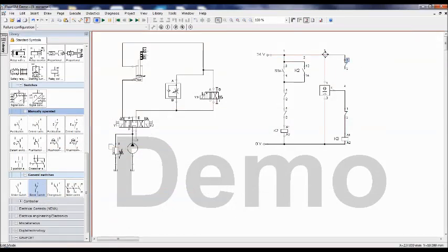Why this latching is required, I'll tell you. B1 sensor data can be lost. If the cylinder rod is not in the position of the B1 sensor, it will be lost. Still we want to have a slow movement, so in that application it is required.